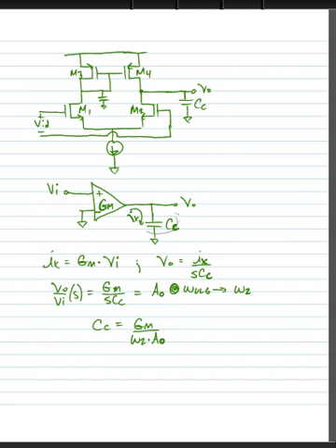Narrowbanding is inefficient, and we're going to start using a technique called pole splitting, where we're going to smartly place a capacitor that will cause the poles to split apart from one another rather than just affecting one pole like we're doing here. So in this case, all we're doing is modifying the output pole, making it a much lower frequency so that it's clearly much more dominant compared to the higher frequency pole. And we will do that in the Wednesday lecture.